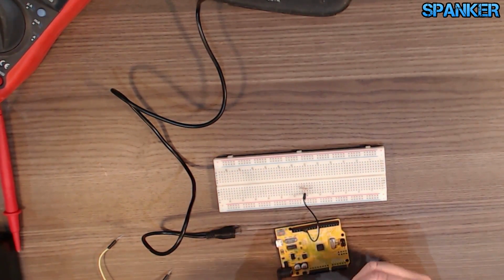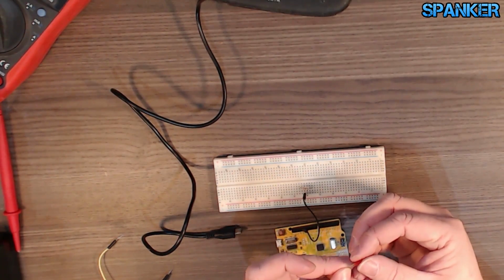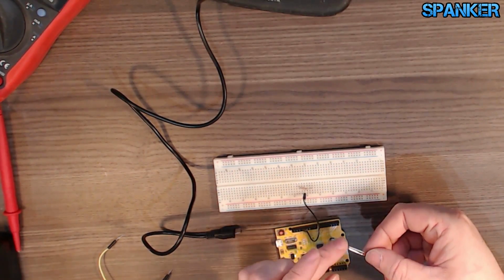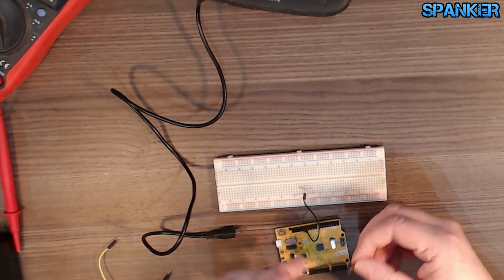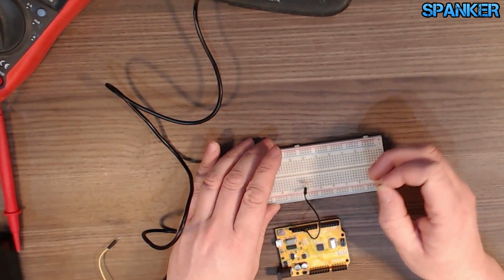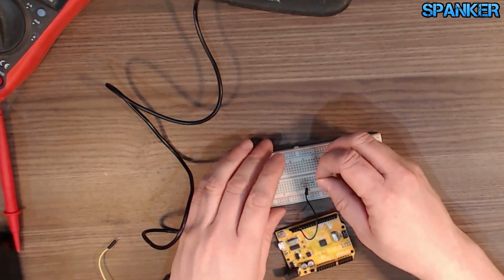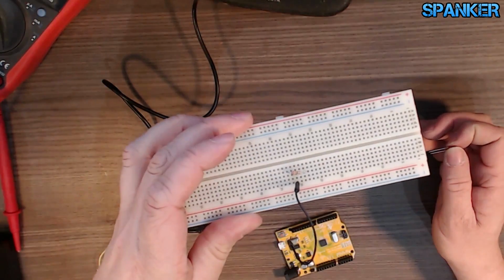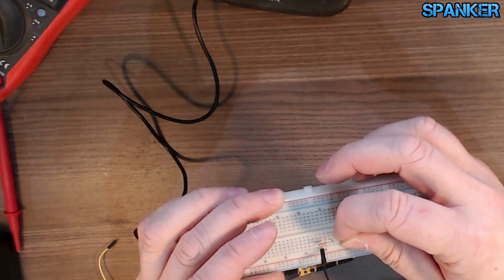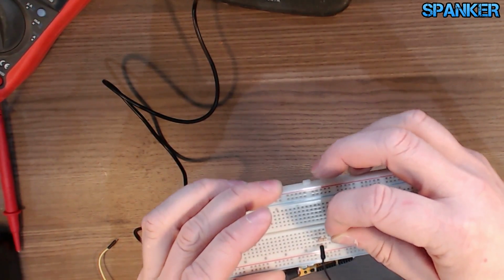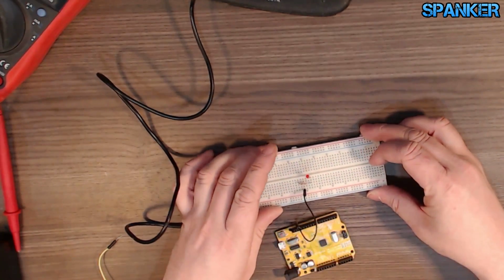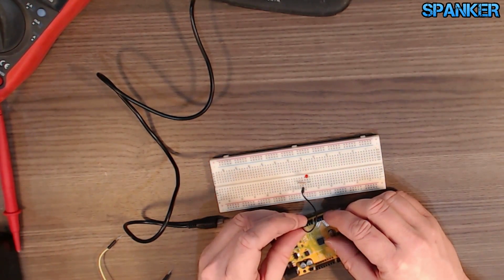And then we've got another LED here. With LEDs, the legs tell you the polarity. Positive is the longer leg. So on the same track as that second leg of the resistor, if I just disconnect that and pull that up, we're going to pop in the LED, same track as this leg, and put it into the next track as well. So the LED then goes in there. And so that goes back to pin 13.